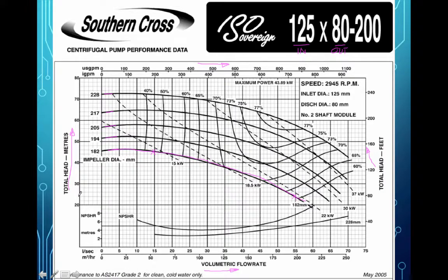That's pretty typical behavior. When we get to 0 liters per second, these points here are called the shutoff heads. And they're the heads that a pump will generate at just slightly above 0 flow rate. Technically 0, but it's in a dynamic equilibrium.